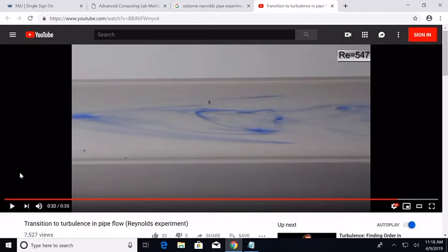Mixing is essential because any chemical you make, you have to mix different constituents until you get the product you want. In combustion, what are we mixing? In our cars, we're basically mixing air that's injected into the engine and fuel. And they should be mixed well, otherwise we'll just throw them out through the exhaust before they burn completely. If it's not mixed well, the fuel will not burn. So turbulence is very important. So that's a big advantage.